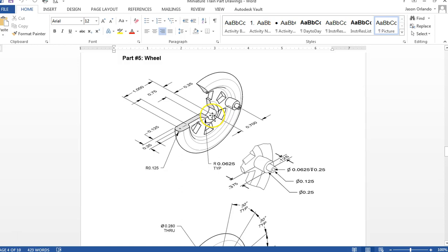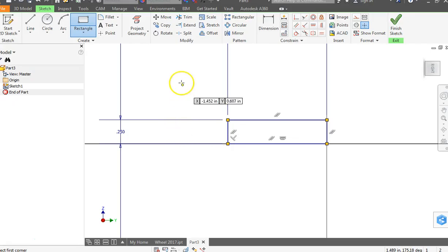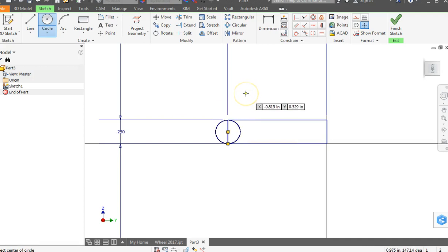Now that's coming from that center line, right? Okay, so I've got the semicircle on the end. How about we do that real quick? I'll add a circle. I'm going to hover and find the midpoint there, right there. And I'll just go to the corner. It gives me the correct width. I can use the trim tool and cut this piece off. It doesn't want me to trim that because of the dimension, so we'll just leave it for now.